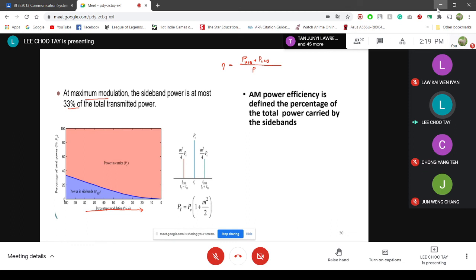Practically it's very difficult to actually split your upper sideband from your lower sideband. So what Weaver suggests to improve the situation is to perform a two-stage single sideband modulation. In the first stage, we modulate the baseband signal with a low frequency carrier.